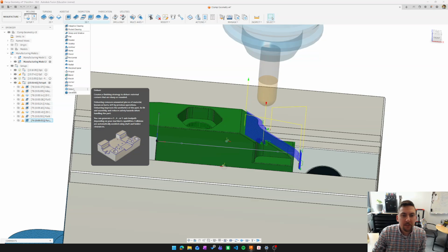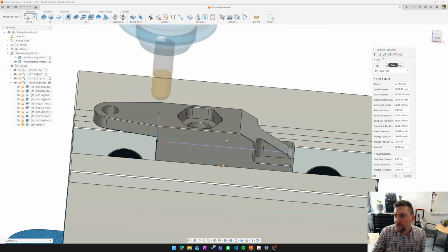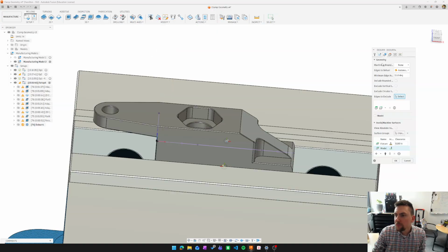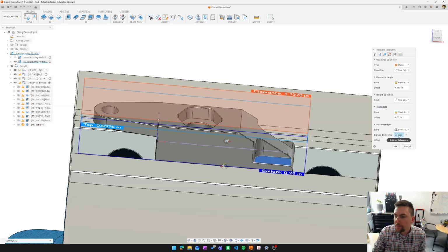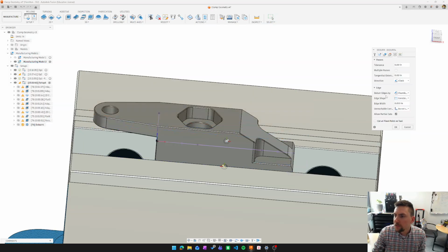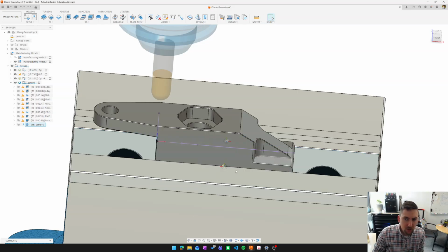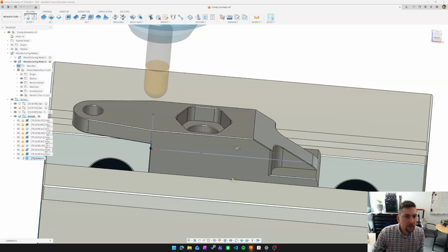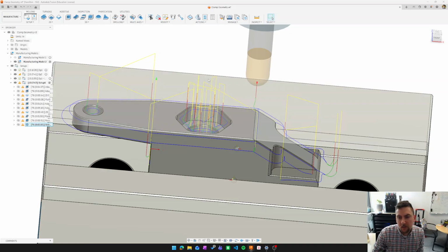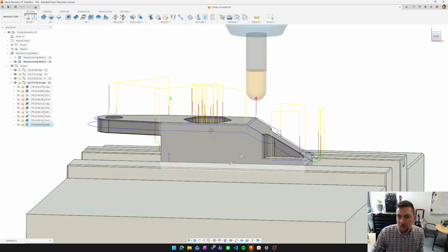So I'll run 3D deburr, run our 3/8 inch ball again. We'll set our geometry. Don't really need to do much here. I will change our bottom height to selection. Pick that bottom face. Passes. That's fine. Let's see what that does. It should automatically avoid our vise since we added our fixture in there, and it does. It's pretty handy.